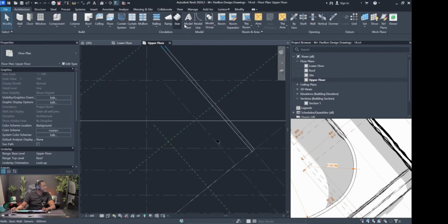By the way, when you're doing this section, guys, pay attention to where the grid lines are in relation to the object. I know that it's a sketch, so you can't really make it out, but you can tell when it is centered to the left or to the right, because this matters in how the curves come together. For example, if you look at this line here, you can see that this is justified to the right of this low wall, but this grid line here is in the center of the wall. So keep an eye on that when you are creating this section. Where is the center line?